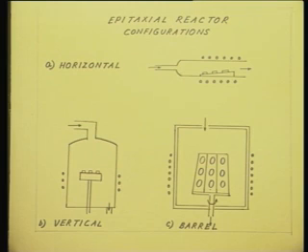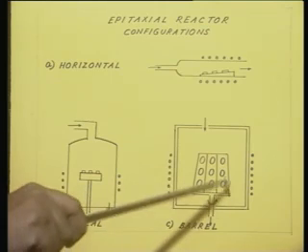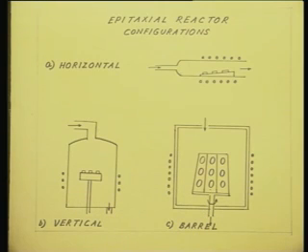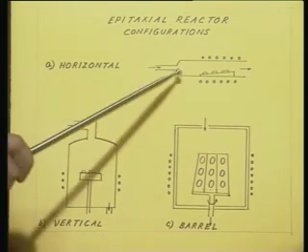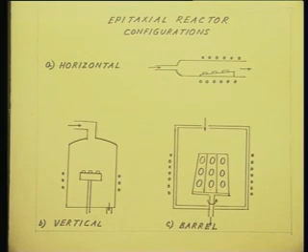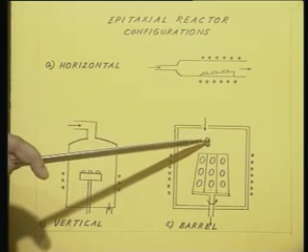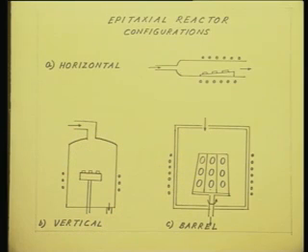So, you put one whole silicon wafer in each of these grooves. You can rotate the barrel for better uniformity of deposition. Remember, a barrel reactor is also essentially a horizontal reactor because the gas flow is parallel to the semiconductor sample surface.